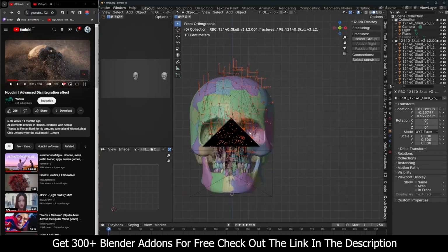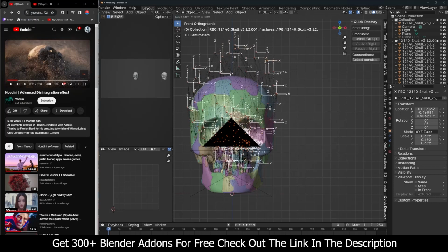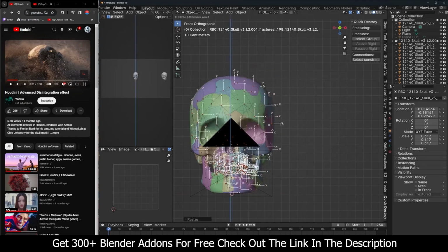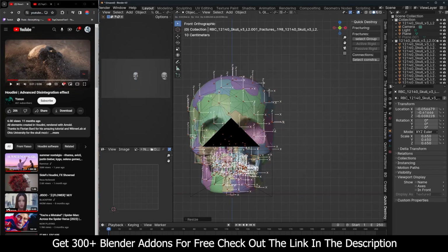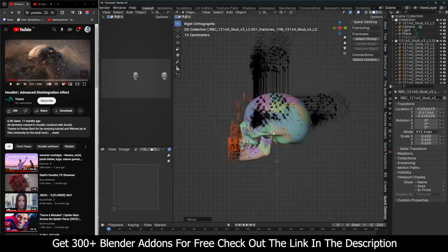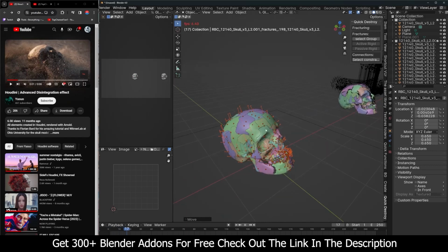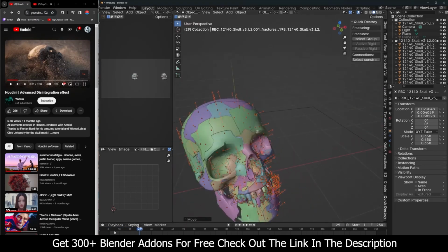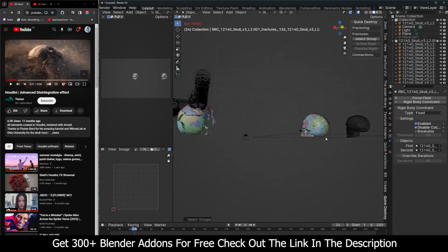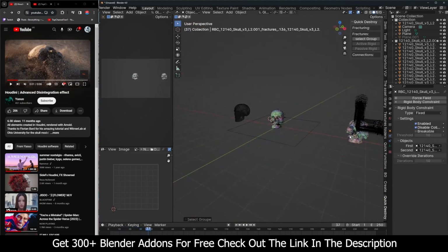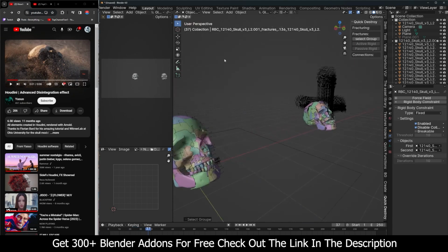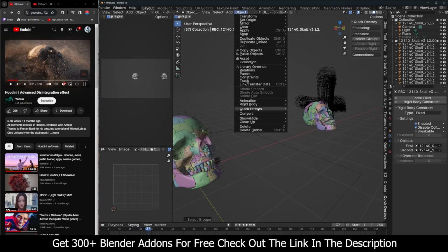One thing I couldn't figure out is the shape always comes up a bit offset and not in the exact position. So you can usually just scale them up and move it a bit until the pieces line up correctly, and I have to do this from the side as well. If we hit play, you can see now we get a better connection with less gaps between each piece. Now you can see this holds up much better than this done using the connect add-on.